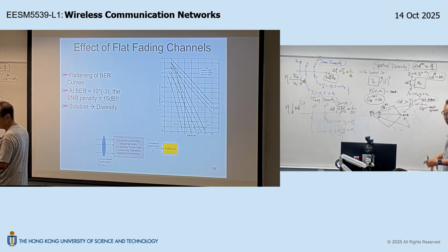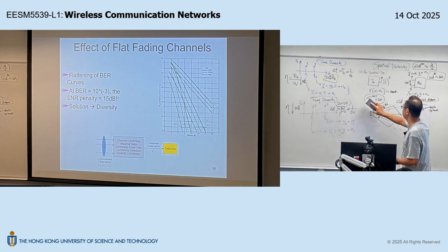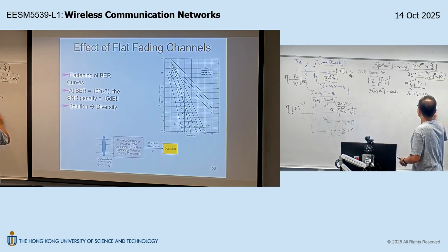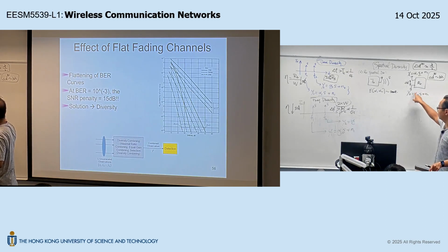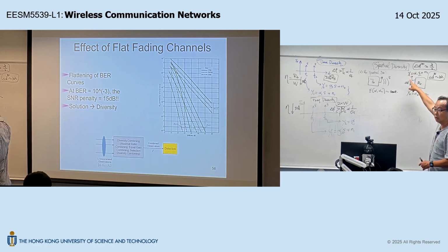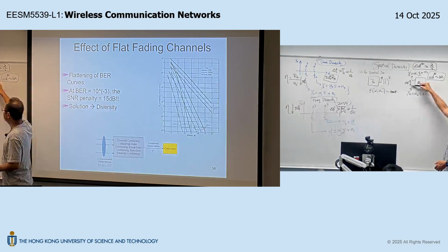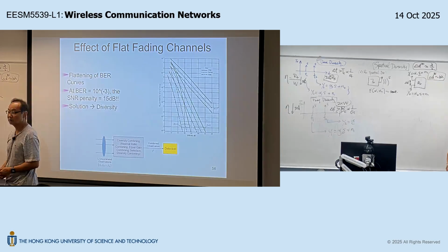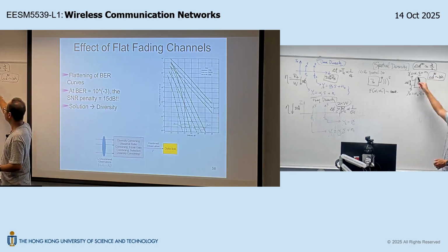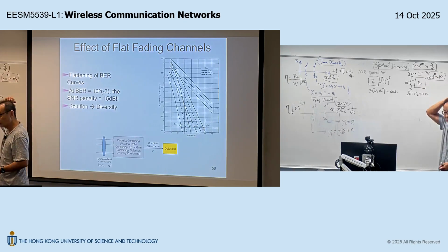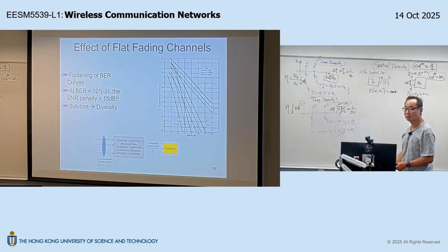So that is something we haven't seriously talked about, but now just for completeness, let me introduce these parameters. In order for us to have diversity observations, the spatial separation of, let's say, the mobile receiver needs to be at least half lambda, okay? If you maintain this condition, then this fading coefficient will be independent. Then you created 2 diversity observations. Is that okay?